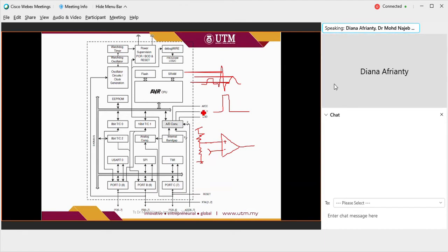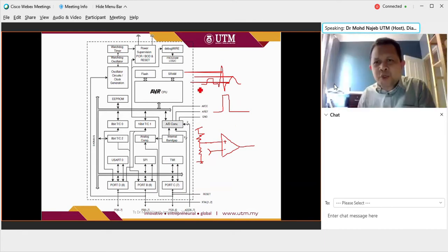Through some circuits, you can actually convert this ECG signal into a square wave, so one peak will become one square wave. Let's say you want to use the built-in analog comparator, so that when it goes over a certain voltage, it will trigger the microprocessor or certain registers inside to capture the event of a pulse. Let's say you have another pulse over here.